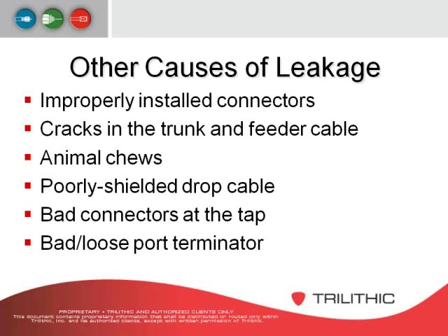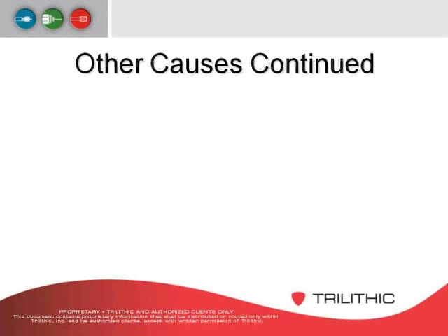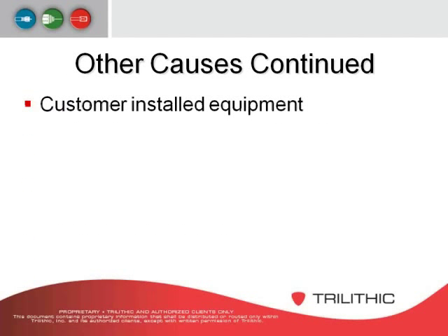You'll find that most of your signal leaks, when you start troubleshooting them down, a lot of times they'll come from loose connectors. Loose connectors are huge issues. That's one of my personal pet peeves, making sure that whenever you put a connector on, you snug it, you tighten it up to where it doesn't vibrate loose and things like that. You want to make sure that you tighten your connectors. And then corroded connectors. And the list goes on.